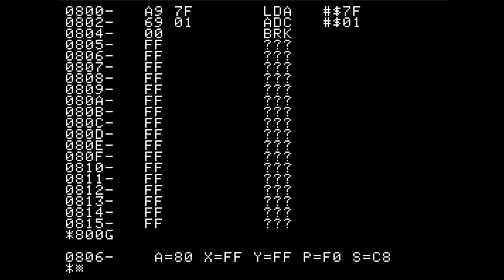Moving to the right, we hit the D flag. Unlike the other flags, this isn't really a read status. It's meant to be set by the programmer. If you set the D flag high, all of the arithmetic in the CPU is done as BCD, or binary coded decimal. Even in the 1980s, hardly anyone used BCD, so you will rarely have to deal with this flag. Your main concern is making sure that you don't turn it on accidentally.